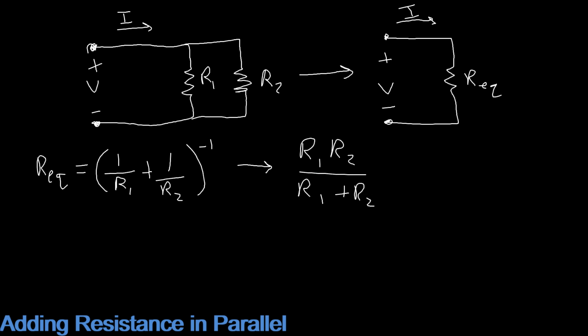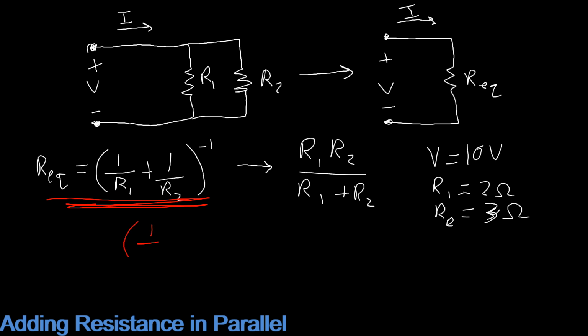So now going back to our previous example. Now once again, when solving for the equivalent resistance across parallel resistors, we're going to be using this new formula given to us right here, is equal to the inverse of 5 over 6 ohms, which is equivalent to 6 over 5.